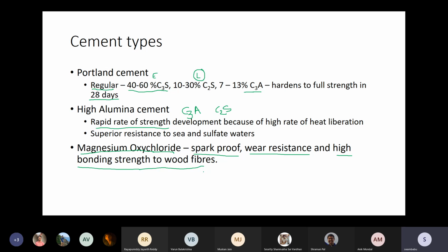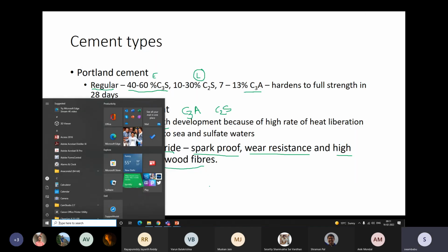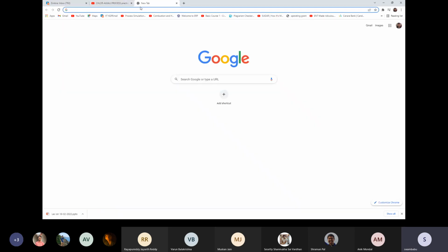But the wood alone doesn't protect from the weather conditions, so they will stick some bricks with the wood fibers, whatever wood. For those, they cannot use Portland cement. That won't work for them. In such cases, they will use magnesium oxychloride. I'm sure you would have explored this. I lived in Australia for a long time, so I know.